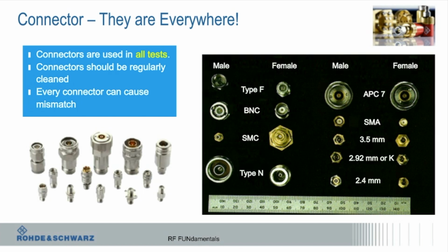Okay, so SMA is not a precision connector. If you look at an SMA, you'll see white stuff with a little metal thing in the middle. That conductor in the middle is, more often than not, somebody gets a piece of coax, strips off the ground shield, and sticks a connector on the end.